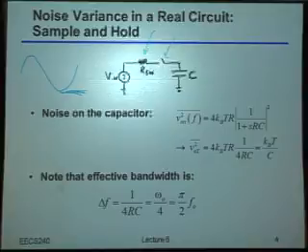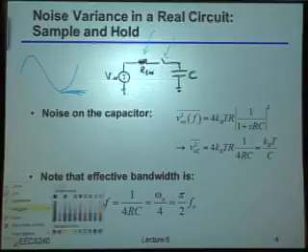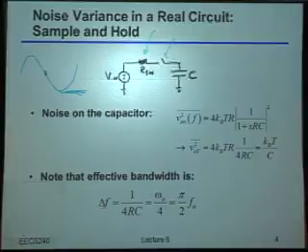And well, once you have that resistance, that resistor is, of course, going to add some noise onto the actual voltage that you measure. And so, of course, when you turn off that switch, you're going to also sample that noise, right? You could get a slightly wrong sample out of the circuit. Okay? So let's quickly calculate what the noise on the capacitor should actually be due to the thermal noise of the source or switch resistance.